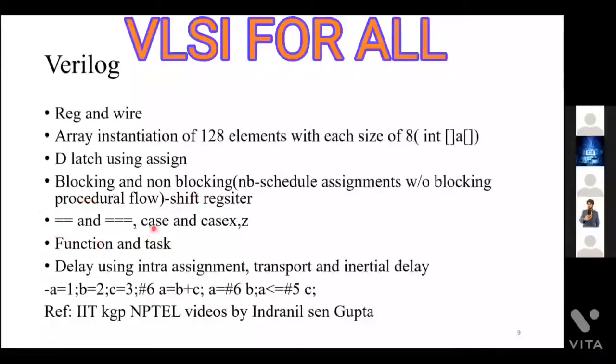And the same thing for case, casex, and casez. In the case, 0, x and z are considered, whereas in casex, x is considered as a don't care, and for casez, x and z are considered as don't care. These three are synthesizable, and after synthesis, all the three are almost the same. And you can see the difference between the function and task. The function is going to provide you a single output, whereas task is not going to provide a single output. From using the task, you can generate multiple outputs. You can check the difference.